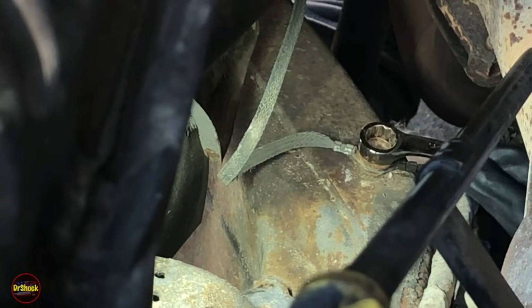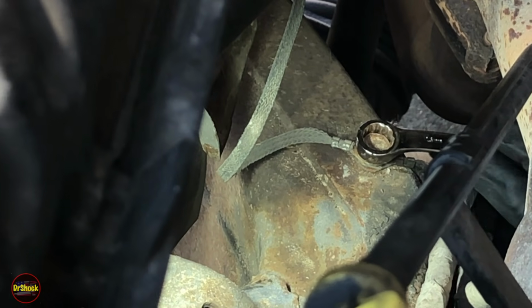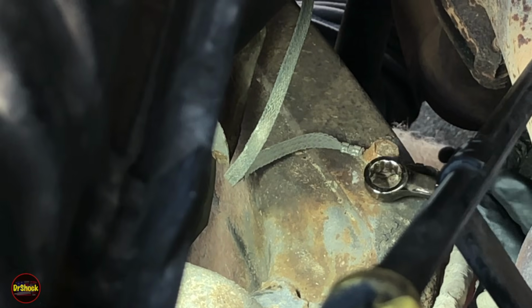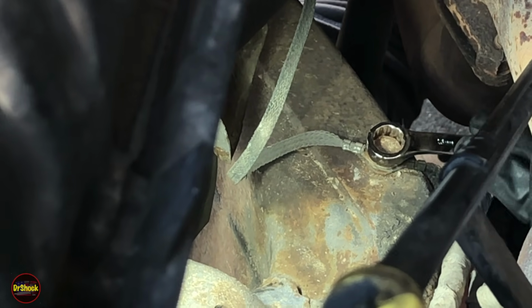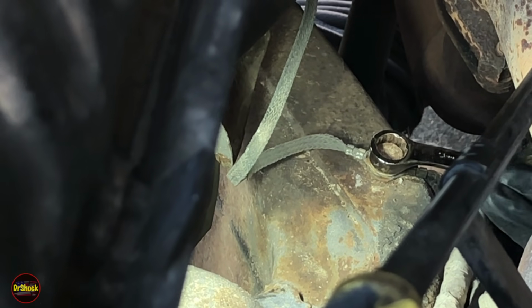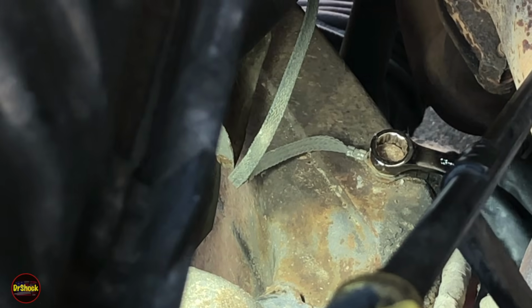All right, guys, I'm underneath here, and what's working for me is a little 13 millimeter stubby wrench that you can see me using here. And it's a little slower than the ratchet, but it allows me to keep my thumb on my other hand holding on the straps so it doesn't turn. So we're just going to work it off like this, and then we'll take a look.